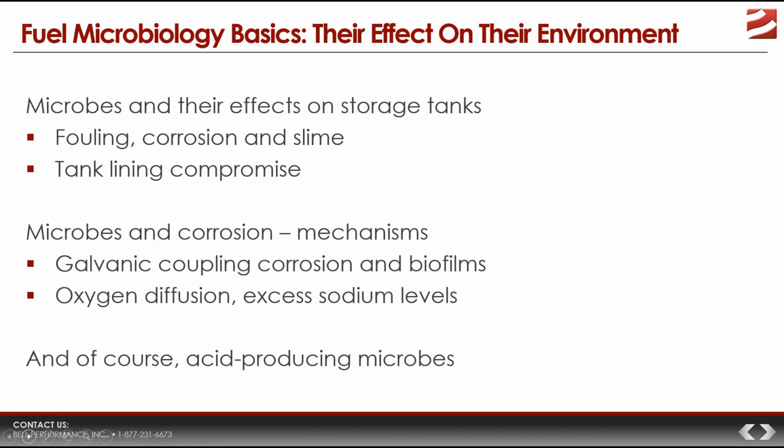Or those can contribute to the production of these localized high concentrations of carbon dioxide, which, if there's any water present, will dissolve in the water, and that will produce carbonic acid, which is highly corrosive to steel, of course. Now, how quickly does this happen? The literature value for diesel tanks between 0.3 and 0.5 millimeters per year is common. Gasoline's about a third that.